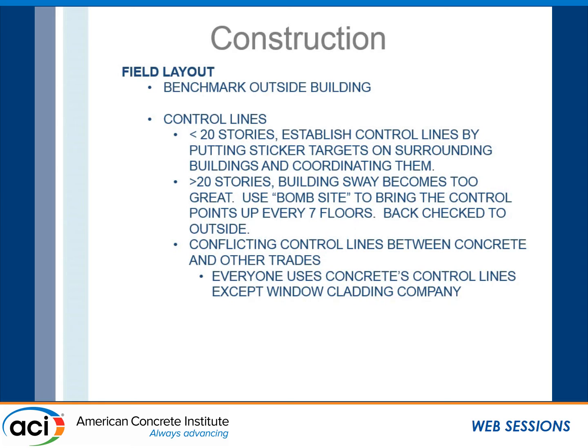There's a constant issue and challenge with conflicting control lines between concrete and other trades. Our rule is that everyone uses the concrete's control lines except for the window cladding company. Because they're bringing up their own thing and what they're shooting for is true and plumb. But all the interior finishes use our control lines.